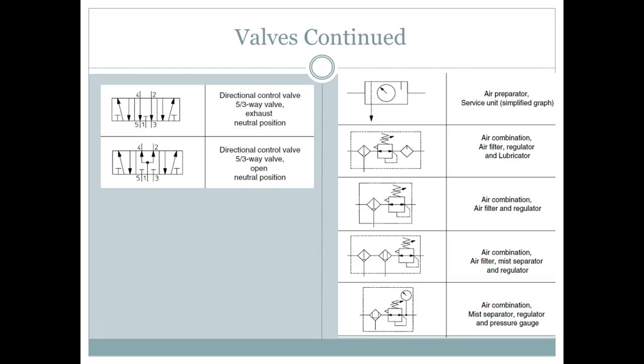So in pneumatics, for a long time we've had a filter, because you don't want any dirt in your air getting into your actuators, because it causes wear. We've had some way to remove the moisture if it gets into the air, because that's the problem we have with air and moisture, right? Anytime the air heats up and then cools down, it's going to condense if there's any moisture in there. So we've got some way to remove the water, some way to remove the particles, and some way to adjust the pressure. So we have what we call a pressure regulator.